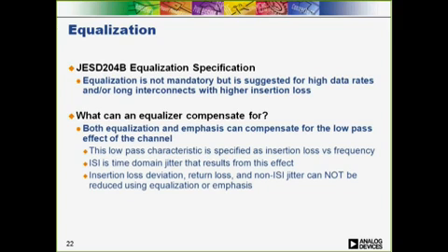Both equalization and emphasis can only compensate for the low-pass effect of the PCB channel. JESD204B defines this in terms of insertion loss versus frequency, and ISI is the result of this effect. Neither equalization nor emphasis can compensate for insertion loss deviation, return loss, or non-ISI jitter. This will be especially important to remember when considering possible trade-offs when laying out the PCB, and we'll discuss these later in the presentation.